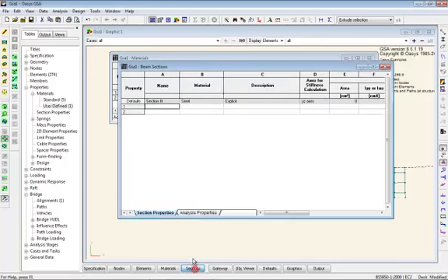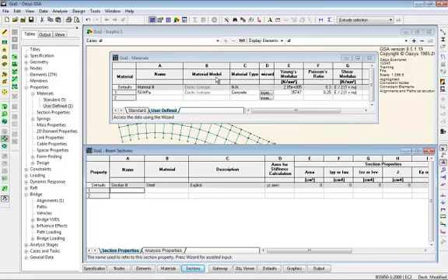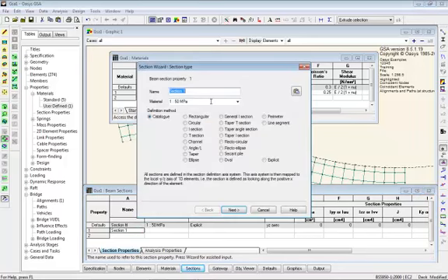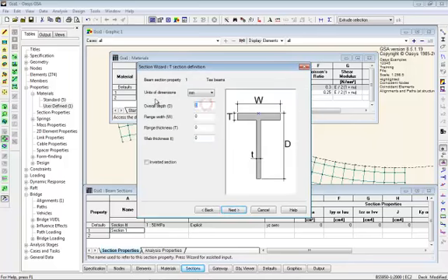And then I'm going to create some sections and just default my concrete material there. So let's say T-beams, my longitudinal ones, 3 meters wide flange, overall depth, the flange, the decking thickness, or the slab, and the web thickness.